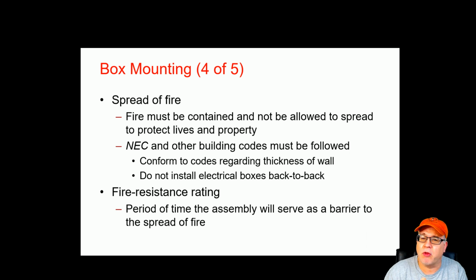But in residential, we also have to remember that we have to draft stop. We have to stop the spread of the potential fire. So that stuff's all covered in the National Electrical Code, and this program gets into more detail about that as well. So, spread of fire. Fire must be contained and not be allowed to spread to protect lives and property. NEC and other building codes must be followed.